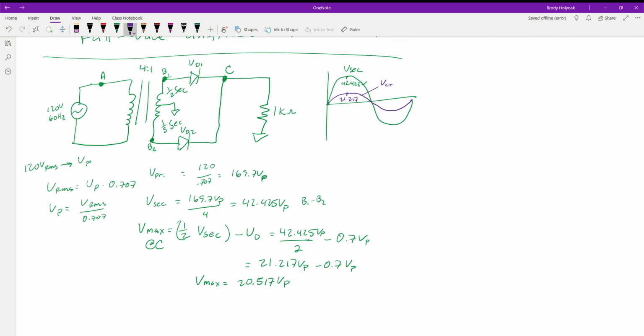So what's going to happen is on the positive cycle, this half is going to come up and around and go through here, and then it's going to come back in through the ground, and then come back the other direction. Then the other part of the wave is going to come through down here, but because the voltage is coming on the opposite side, in comparison to B1, B2 is going to be inverted 180 degrees. That's one of the cool things with transformers. If we take these signals, one off the top, one off the bottom, with the center tap being our ground, we're going to get 2 signals coming out, and they're going to be 180 degrees out of phase, which is what we are looking for.